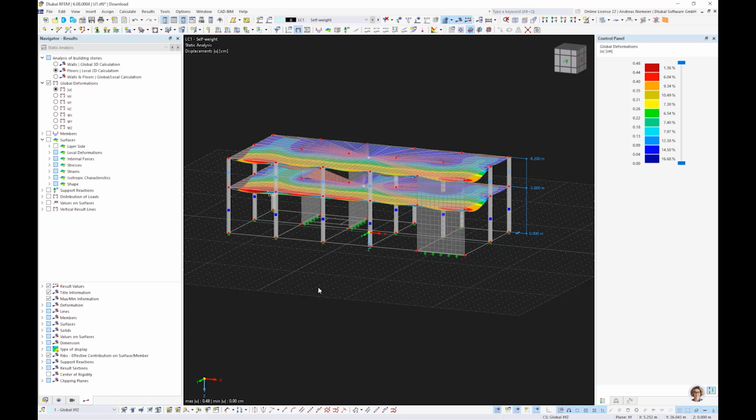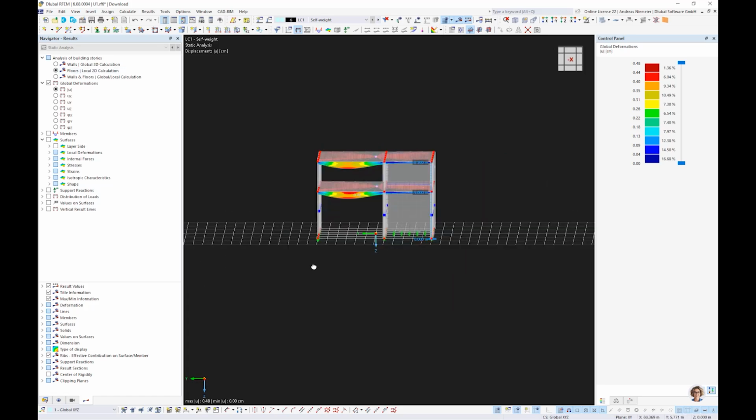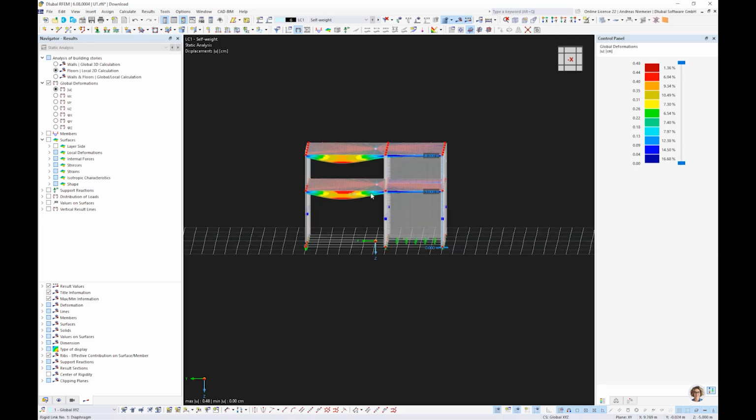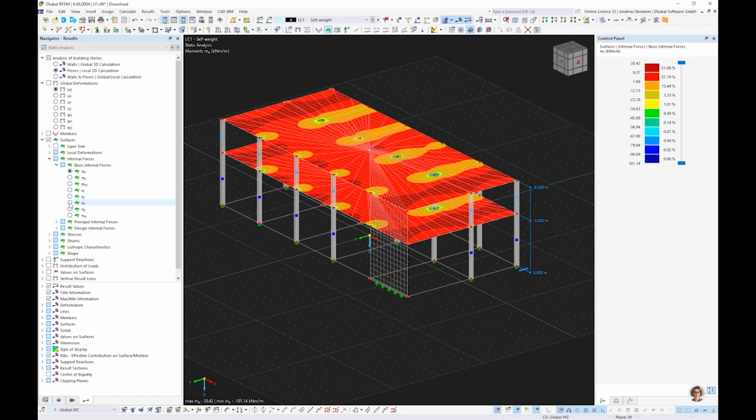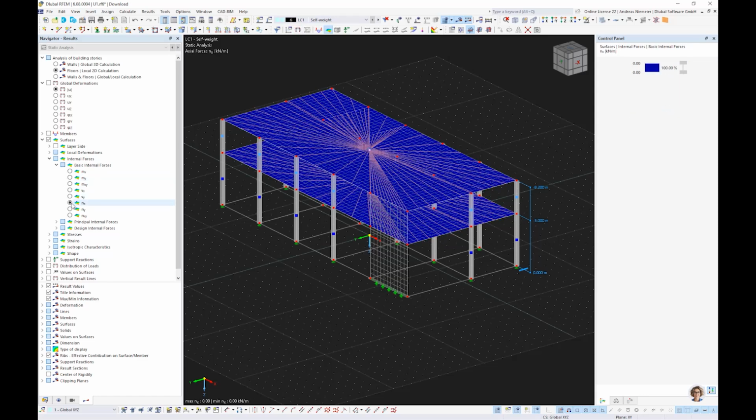You have now, for example, here only floors. This means the program interprets the floors as separate substructure. It calculates the ceiling with separate supports and separately. So I get for these elements only bending moments, but no membrane forces, because I assume these slabs work rigid in plane, that maybe the main structure is working, but this ceiling itself I calculate separately.